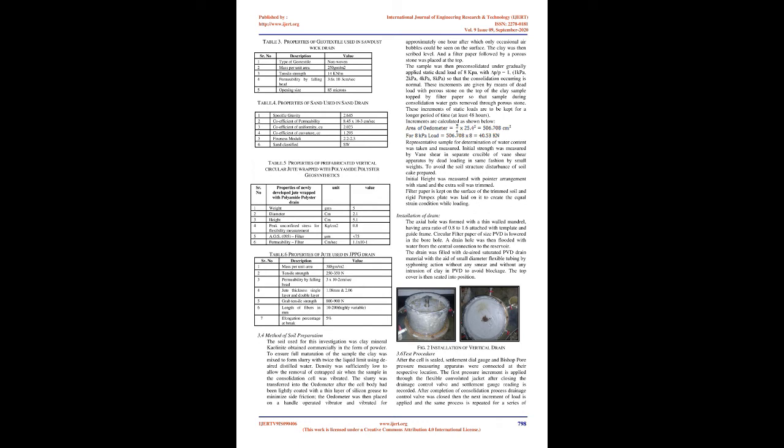2. Vane shear test. The vane shear test is used to measure the shear strength of cohesive soils, and for soils of shear strength less than 0.3 kg/cm2 for which unconfined tests cannot be performed. This test gives the undrained strength of the cohesive soil. This test can be done in the laboratory or in the field directly on the ground. Fig. 1 Vane shear apparatus with soil sample.